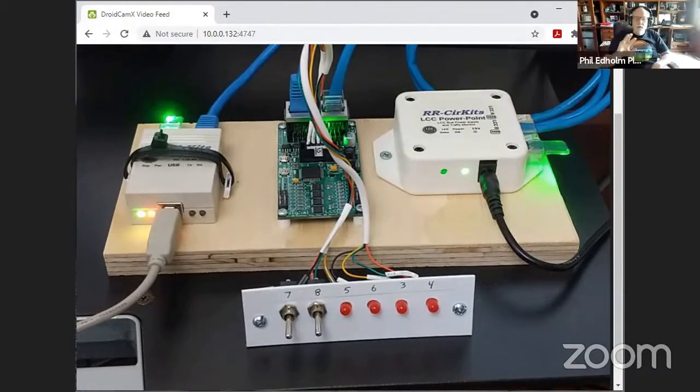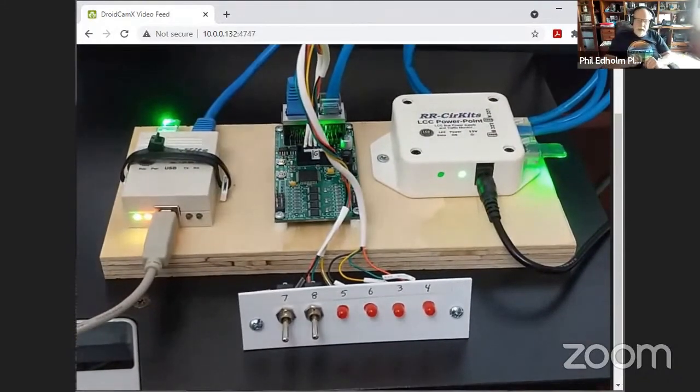I understand it can, but here's the difference. It's a fundamental difference. If I have a protocol bus and I put nodes at the edge, they have intelligence and have to think on their own. They're not dead simple wires that can't fail. And if one of them fails, can it bring the bus down? All sorts of interesting questions. The alternative is to use really cheap wiring to aggregate the intelligence in central locations as CMRI did.